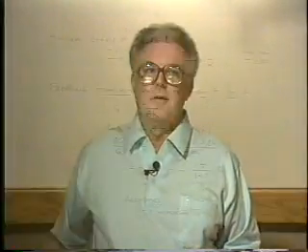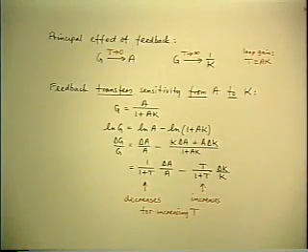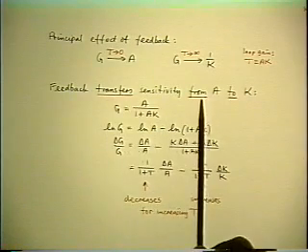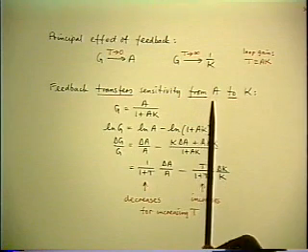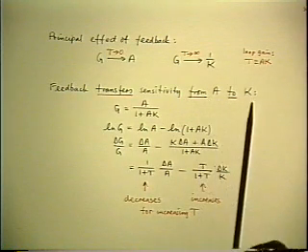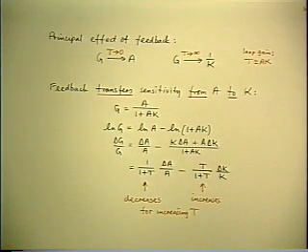That's one of the important reasons for using feedback. So that's a common statement. Feedback reduces sensitivity to the variations of the internal components. That's only partially true. What feedback really does is it transfers the sensitivity of the closed-loop gain from components in the A box to components in the K box. It doesn't get rid of it, it transfers it.